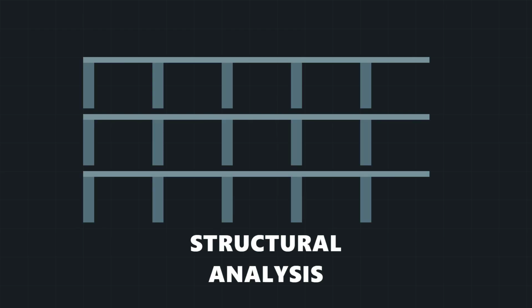Pre-demolition structural analysis identifies all primary load-bearing elements, including critical columns and shear walls. Simultaneous removal of these elements initiates the controlled collapse sequence. Engineers must calculate the structural redundancy factor. Highly redundant structures require significantly more extensive charge placement to ensure complete failure initiation. The analysis precisely determines the exact location and orientation of charges to create a controlled, progressive failure path. The objective is to ensure the structure falls vertically within its established footprint.